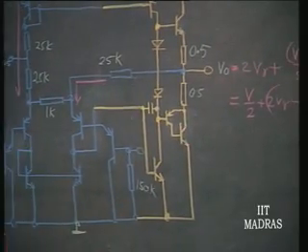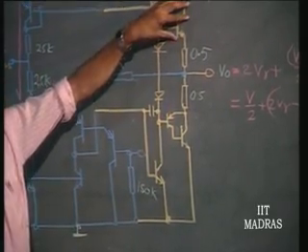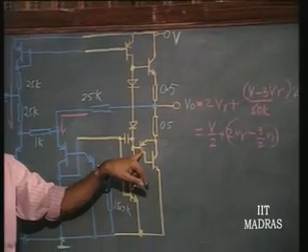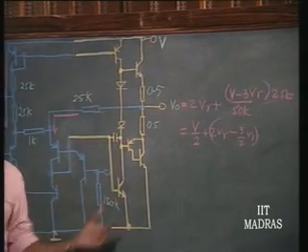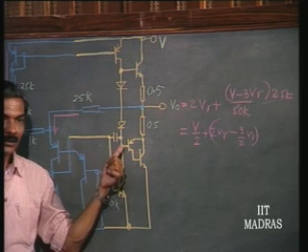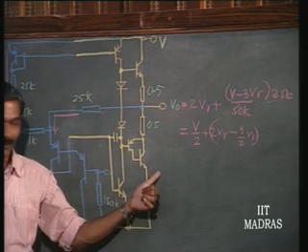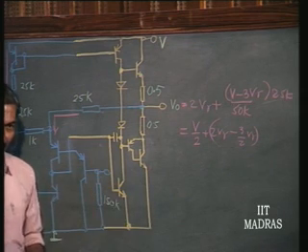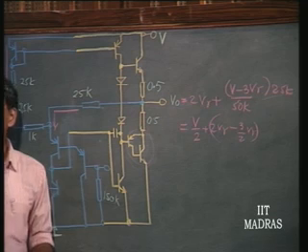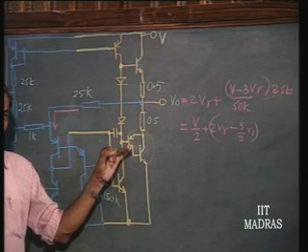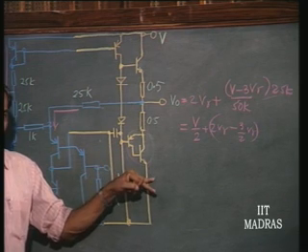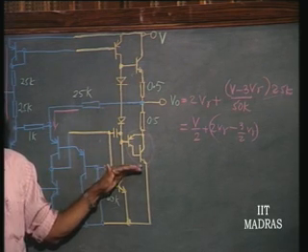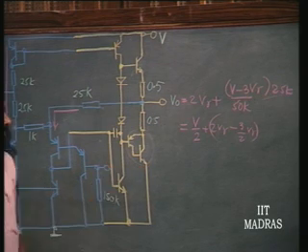Then here, this is another strategy which is commonly adopted. This is the NPN stage, and we should have a PNP here, which is a bad PNP, but what is available. So, in order to make it good, you are now adopting the Darlington pair that is possible, connecting PNP to NPN. Effectively, the gain of this is controlled by the NPN beta current gain rather than the PNP. So, this is commonly adopted in most of the output stages, pairing a bad PNP with a good NPN, so as to make the drive capability of this almost identical current drive capability.